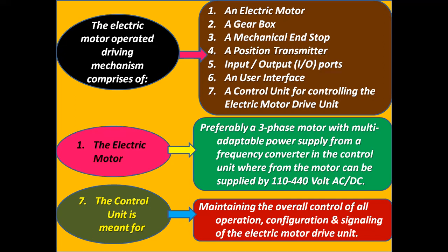Electric motor, preferably a 3-phase motor with multi-adaptable power supply from a frequency converter in the control unit, wherefrom the motor can be supplied by 110 to 440 volt AC or DC.